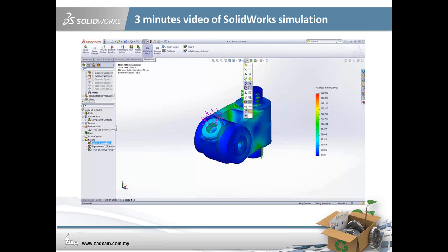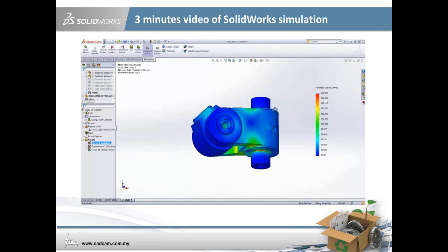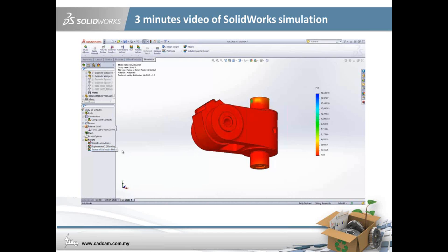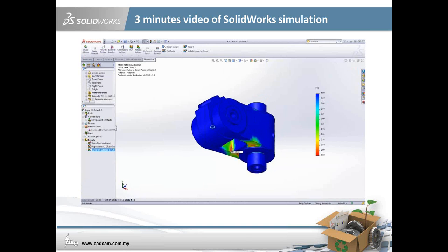The colors on the part correspond to the stress values listed on the right, but since we're analyzing an assembly of parts with different materials with different yield strengths, we'll be better served with a factor of safety plot. This plot identifies the ratio of the stress to the yield strength of each part. For our knuckle, we want to have a minimum factor of safety of 2, so we can change our chart and disregard any values above, say, 4.